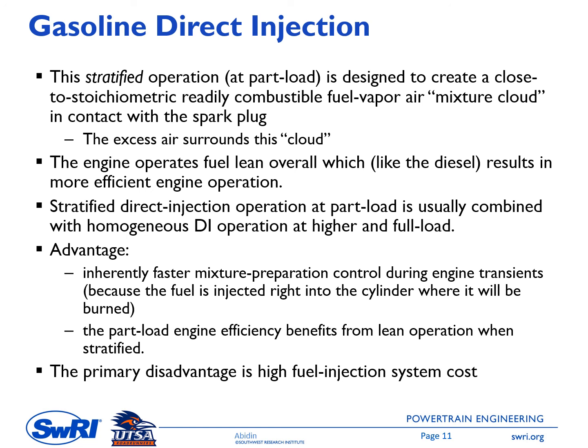The advantage of this strategy is inherently faster mixture preparation control during engine transients, because the fuel is injected right into the cylinder where it will be burned. This is relative to PFI and SPI, where SPI is single point injection. And then there is the part load engine efficiency benefit from the lean operating condition when stratified. We cannot do this with SPI and PFI. So with GDI, once again, we can have a stratified mixture condition during part load, and thus improve the engine thermal efficiency.